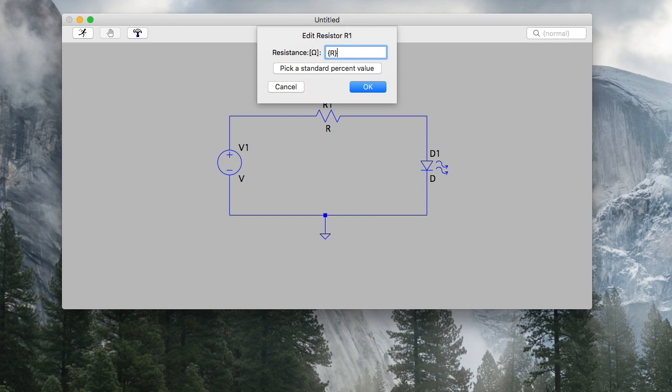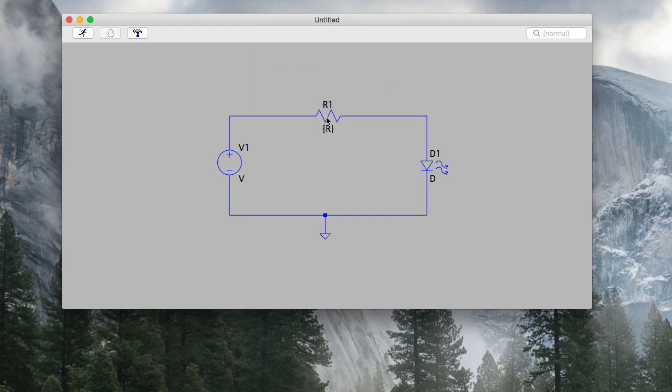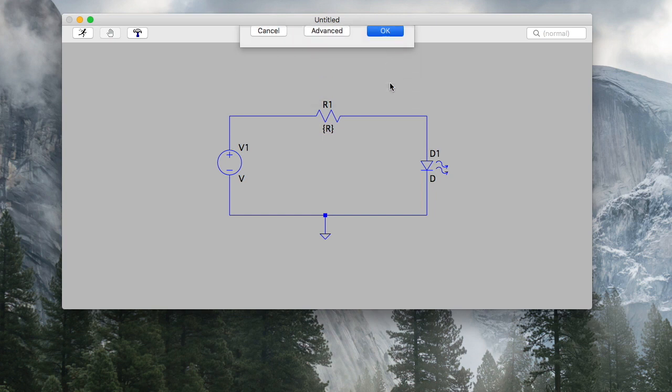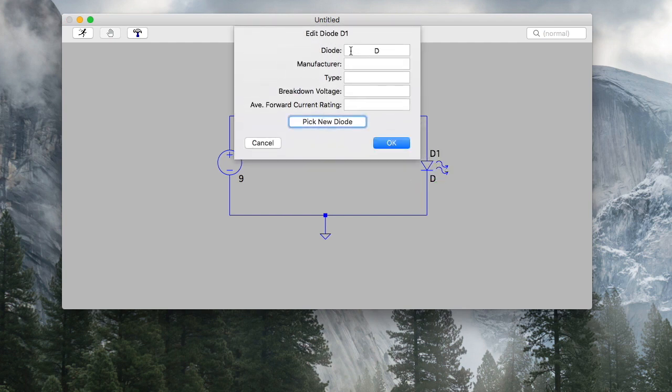Now you'll see most people will take an LED spec'd at 35 and they'll drive it right at 35, the max, and they're very, very bright. If you really want a bright indicator, that's fine. I typically don't do that. I typically drive at half of the rated average forward current for the LED. So you'll see I'm setting my 9 volts.